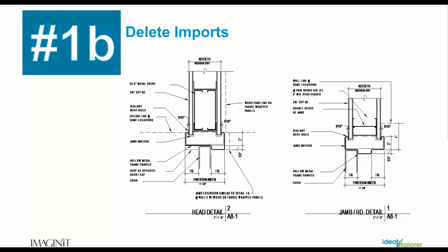If we're dealing with just elements within the model, this is going to be a number one issue for us. So again, did somebody bring in a CAD file? Did somebody explode a CAD file? Where are these things at? How about if somebody did a right-click hide element? How do you find that? It's very, very tough, almost impossible to find that out of the box in Revit. With Ideate Explorer, we can definitely find that information.